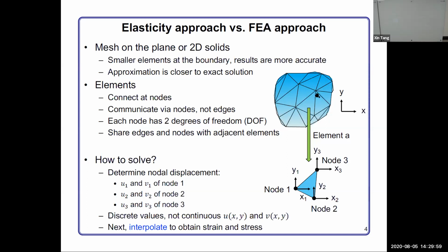As you know, if you took the fracture mechanics or the mechanics of materials class before, if there's a defect in the material, you will have stress concentration. So a coarse element around a defect or around the hole cannot represent the real stress field. It will miss many detailed information. So we need to make the mesh very dense around the defects to capture the authentic stress and strain field. Okay, we will talk about it in detail in the future slides.